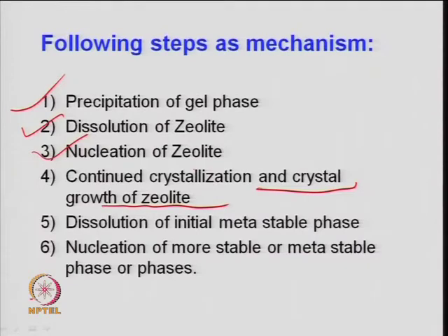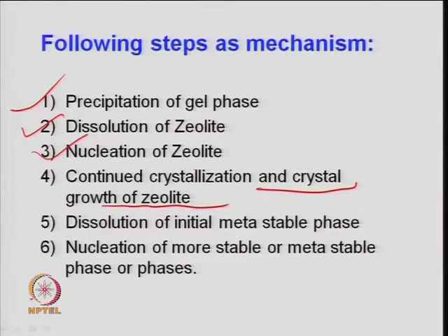So, too much time may increase the size of the crystal, the growth of the crystal, right. That may not be good when you need a nano synthesized zeolite. Sometimes these are desired, right, with very small particle size of zeolite, which may give you a larger external surface area also. That is very important, and sometimes if you look at methane conversion to liquid fuel, this nano synthesized zeolite material may be good. So, one has to look at that also, but the structure may collapse when you have a nano synthesized zeolite material, right.